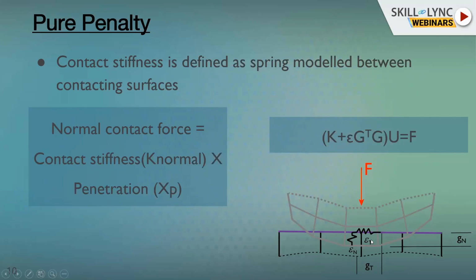We have this tangential stiffness, and we have how they are relatively moving, how much distance from each other. It's not the penetration, it's a relative sliding between the two. Based on that, it calculates the force in the tangential direction. So you can see in this equation, if we move this particular term to the right, it becomes F minus, right? If the direction is downward, the K N, the normal direction force, will be opposing the motion of the F. So this is negative. When it comes to the left side, it becomes positive.